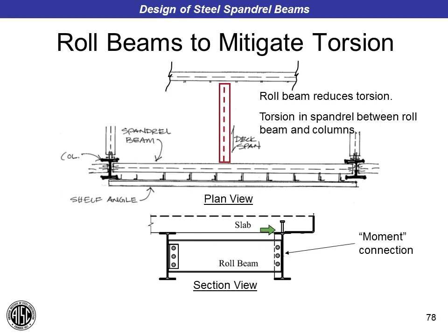And we typically do this by installing a full depth fitted stiffener in the web of the spandrel beam that's welded to the web and flanges of the spandrel beam, and providing bolts here in standard holes, or if they need to be slotted holes, providing slip critical bolts, and relying on this connection to effectively be a moment connection. We're taking the moment or the twist from the spandrel beam out as a couple on those bolts.